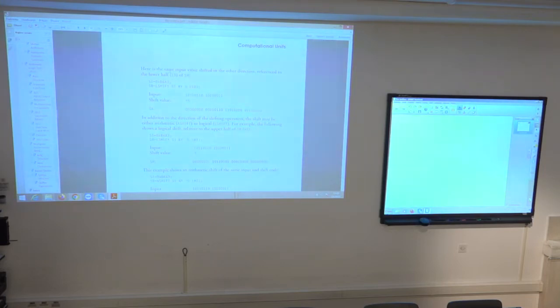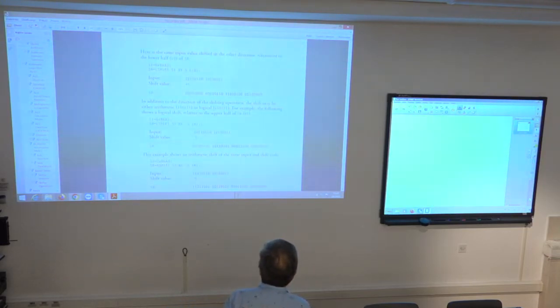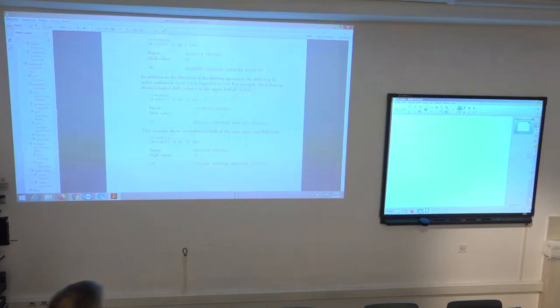And the difference between the logical shift and the arithmetic shift is exactly in handling the sign bit, because the next example shows the arithmetic shift. Arithmetic shift again by 5 positions, relatively high. Since the input value is negative, the most significant bit is set to 1. Then this sign bit is repeated 5 times: 1, 2, 3, 4, 5. And then I have this 1, 0, 1, 1. So the arithmetic shift keeps the sign of the input value as desired.